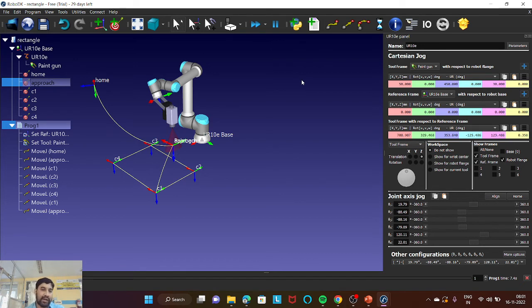At a particular point, the end effector, meaning the tool attached to the robot, will become unable to rotate or move because of its rotation. It is unable to reach the particular target, and that is called singularity. So at a particular moment, it is not possible to rotate the end effector because of its workspace limitation and rotation limitation.